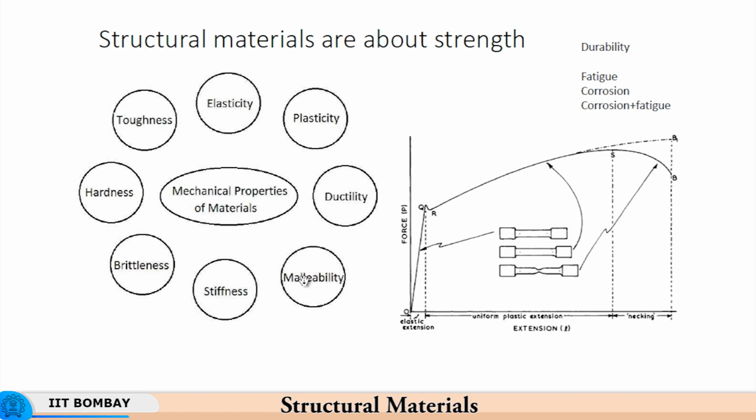So conceptually they are similar, but they are different in the sense that resilience refers to the elastic region, whereas toughness refers to energy absorbed during permanent deformation or plastic deformation. So, naturally, for talking about toughness, it is understood that you have crossed the yield point, the point at which permanent deformation takes place.